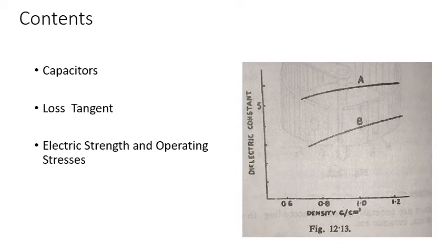So what is meant by impregnated paper capacitor? The impregnated paper capacitors are constructed by rolling paper as insulation between metal foils and filling with an impregnant. They are relatively inexpensive, have a high capacitance to volume ratio, and are capable of working at reasonably high voltage.